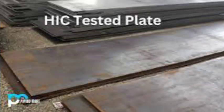Can I add something? Yes. Can I add? Yeah, actually, in some specification, there is two criteria. Sour service is there, but in that specification, sour service means sometimes moderate sour and sometimes severe sour. So in the severe sour, HIC testing is mandatory, and where in the specification it is mentioned that moderate sour service, in that case, HIC is not mandatory. In some specification, it is mentioned like that. So maybe that specific specification he is saying.